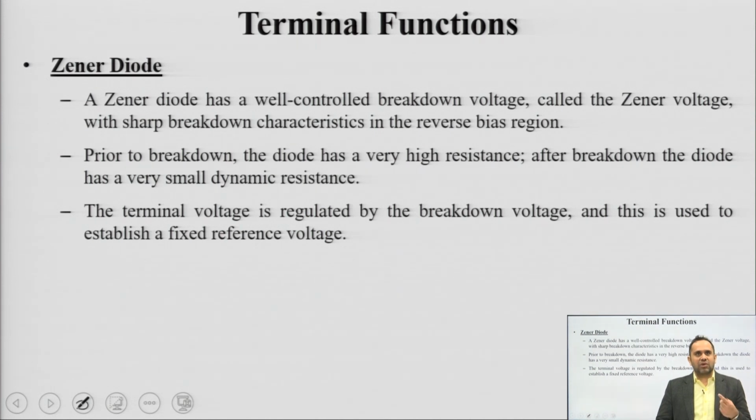So, the reverse breakdown of the PN junction is going to occur at small breakdown voltages, and this behavior can be used to produce a voltage regulator or a Zener regulator. After breakdown, the resistance offered by the Zener diode is very small. So, the voltage across it remains fairly constant. Any excessive current is absorbed by the Zener current after breakdown, because its resistance is very low.